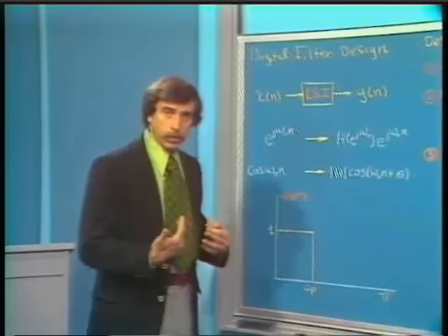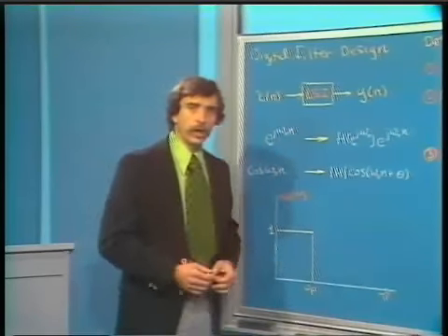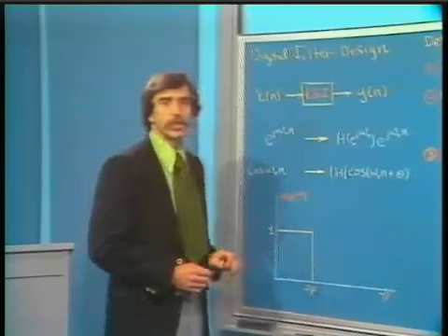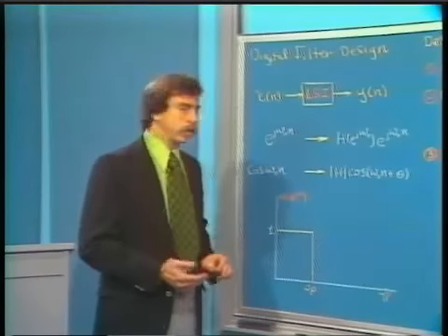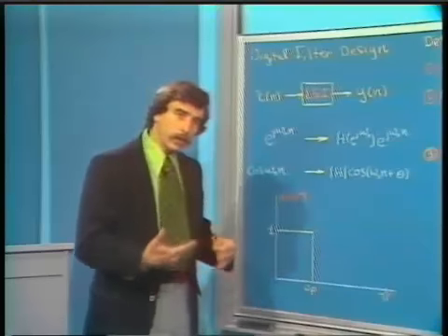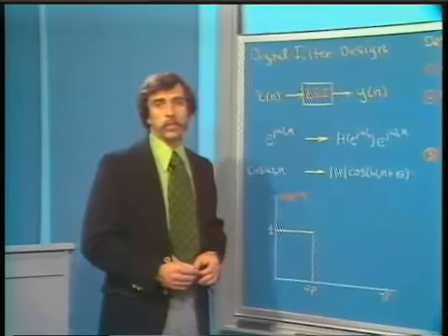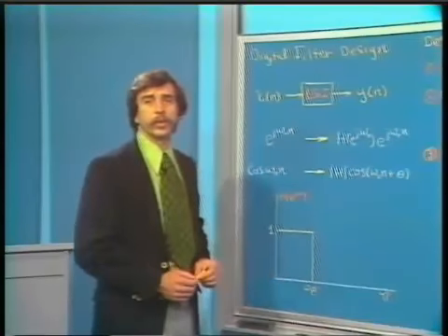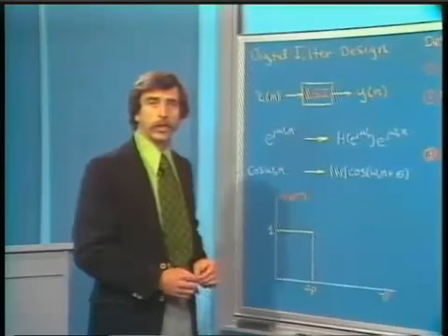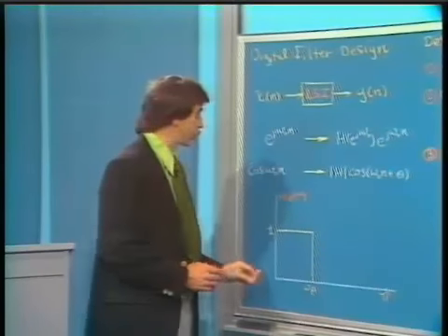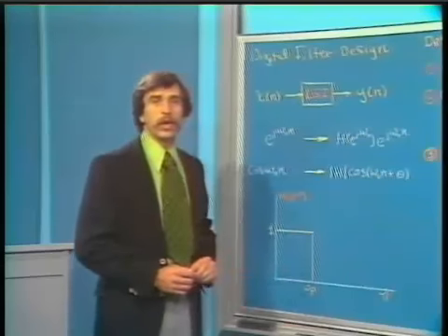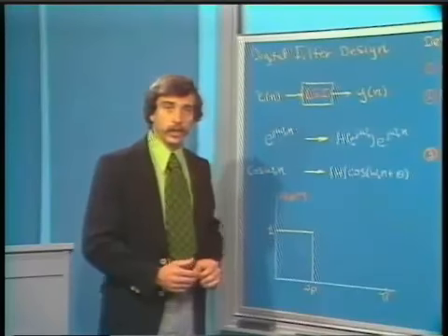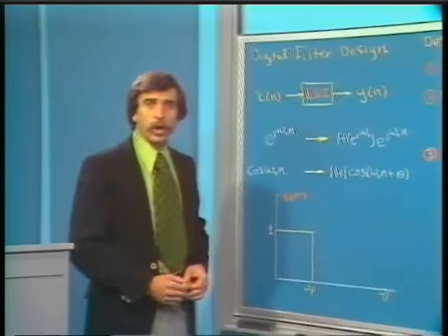We can talk about a wide variety of problems where the desired frequency characteristics are not piecewise constant as they are in the frequency selective filter case, such as the case of a differentiator, in which the desired frequency characteristic is linear with frequency, or the inverse filtering problem where the desired frequency characteristic is in general of a somewhat arbitrary shape.